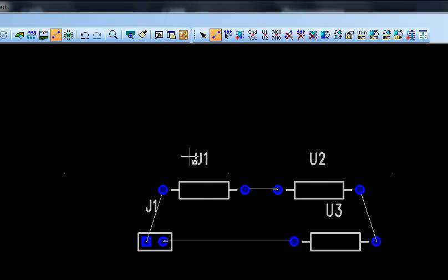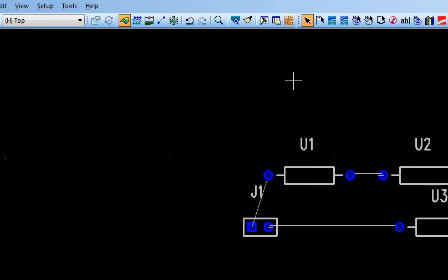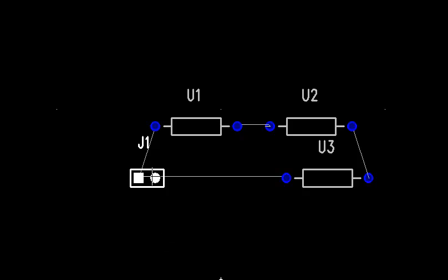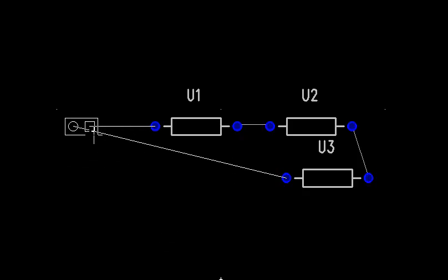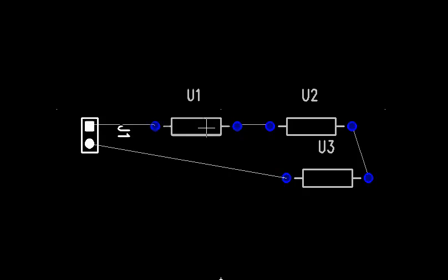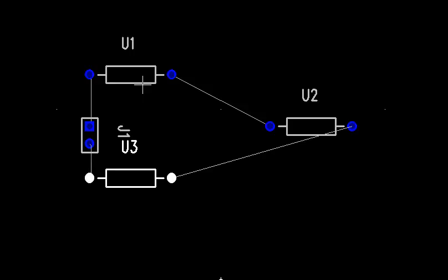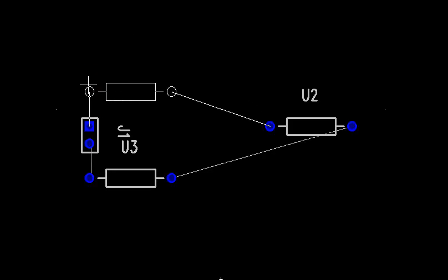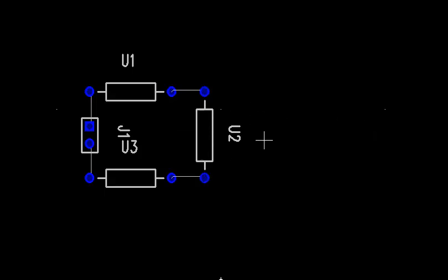Now I'll adjust the layout a bit. So I'll go back to the drafting toolbar and move around the components. I can drag them around. I can also press Ctrl R to rotate them. Something like that. I also want to move around this documentation as well.